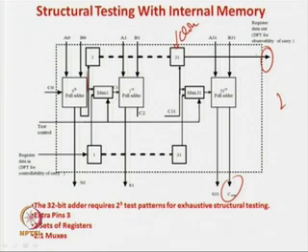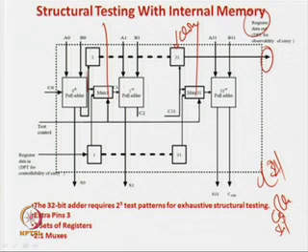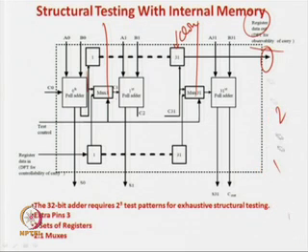So, what have we achieved? If you directly bring out the carry outs from all these adders, then you require around 31 or on the order of 32 pins. Now we require only one clock pin and one shift pin, that is shift out, you can call it data register out, that is the observation of the carry. So, instead of 31 or 32 pins, we have got 2 pins, and we are done with this. But what is the penalty paid? The penalty paid is that we require 32 clock pulses to get the value.